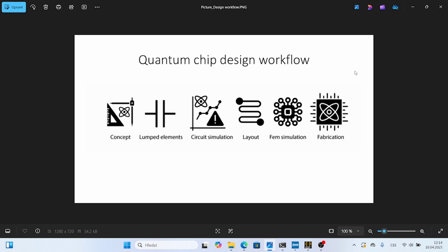For this step, we can use probably almost every foundry you can think of. The only thing is they need to have the capability to manufacture Josephson junction, which is a thin aluminum rectangle. I can think of SkyWater, Efabless, maybe some university fabs or institute fabricators.